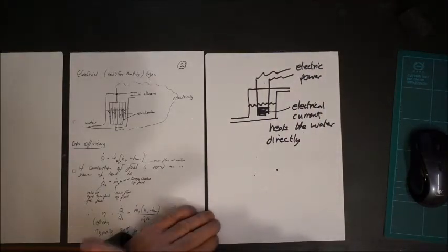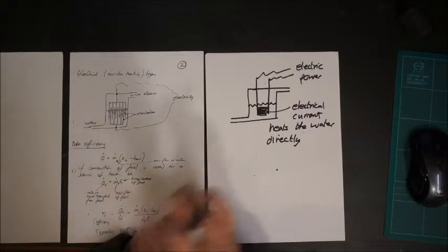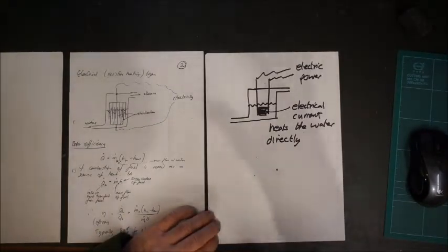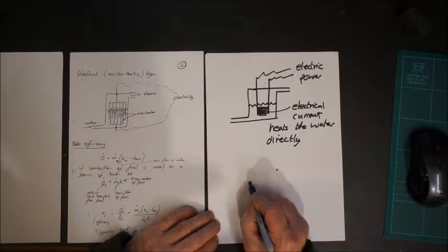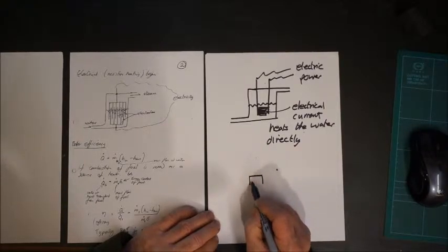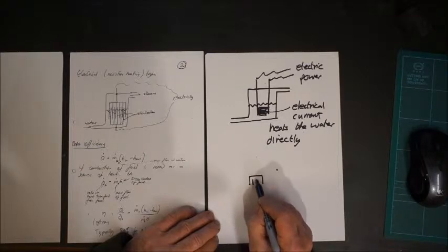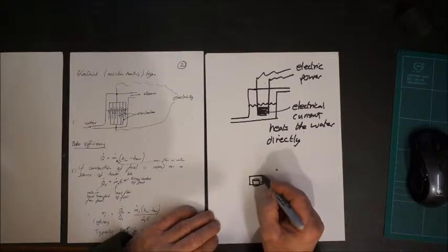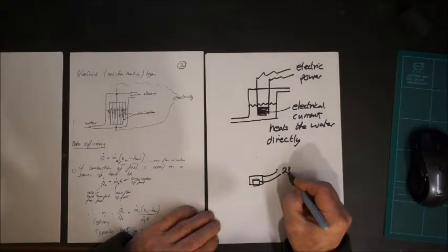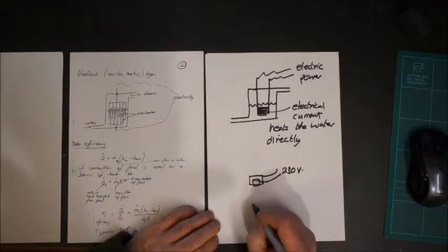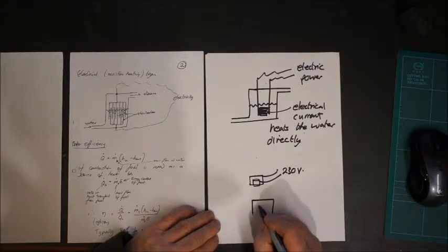We have a piece of apparatus called a Kjeldahl still, which has exactly that, to generate a small amount of steam for the instrument. And all that is just two electrodes, one shaped like that and one shaped like that. So it's just like a little ring, like a can sitting on top of another can, and the electricity is connected straight into the wall socket, 230 volts. I'll redraw that. The outside can and the inside can.